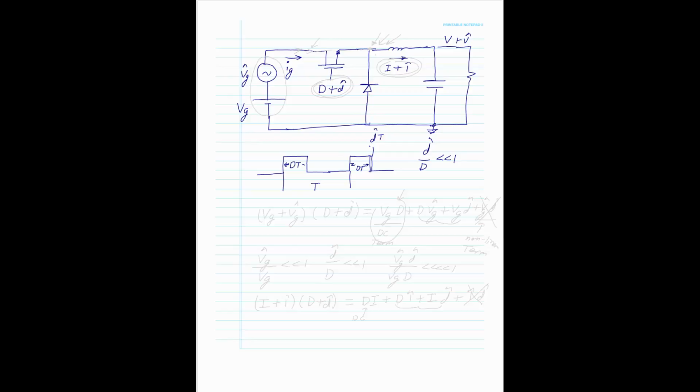So if we look at this and we want to derive something very quick for the small signal, we notice that this point right here, what would it see? Well, it sees really the product of this times the duty cycle. And you can see that from here. That's what generates the square wave across here.